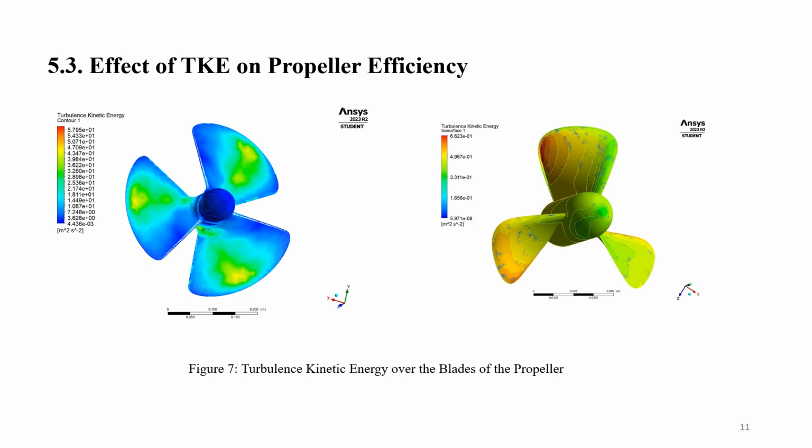Furthermore, high turbulence kinetic energy can lead to various flow consequences that negatively impact the propeller's efficiency. These include uneven loading on the blades, interference with the wake flow, heightened drag, and other flow-induced effects, all of which can compromise the propeller's thrust generation and propulsive efficiency.